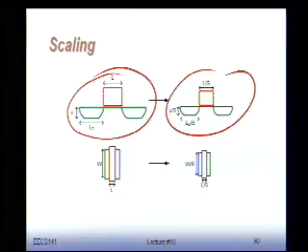I'm not going to talk too much about this, but you can imagine that you cannot keep on scaling oxide thicknesses too much. At some point in time, if you have only 3 atoms, or 3 molecules, on top of each other, scaling down is getting harder and harder. You can go to 2, but then you have a sieve. You can go to 1, and you have no dielectric anymore, basically. Every electron just walks through and is perfectly happy. It's a conductor. So, scaling of all these dimensions.